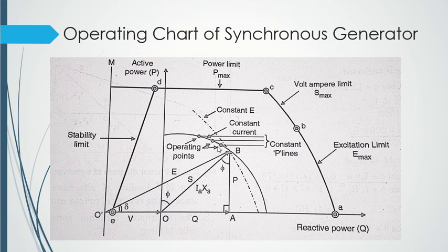If I draw a straight line over here like this, and then measure the sine component and cosine component, different reactive power and active power will be drawn, right? Even though my apparent power will remain as it is, the value of reactive power and active power will change accordingly in order to keep my apparent power equal.